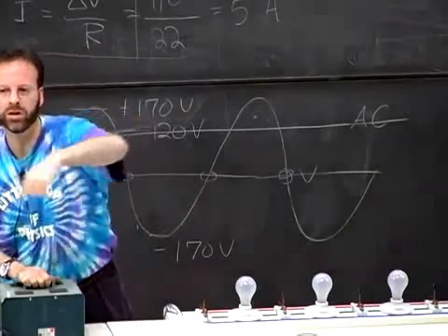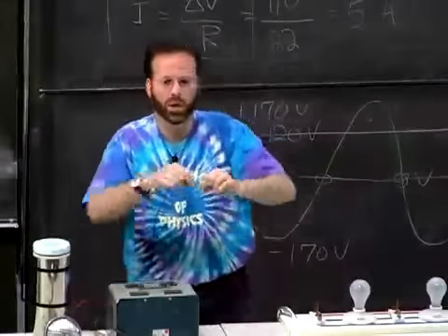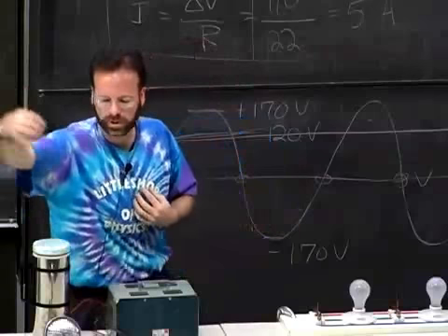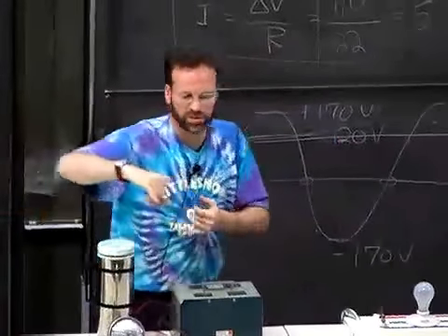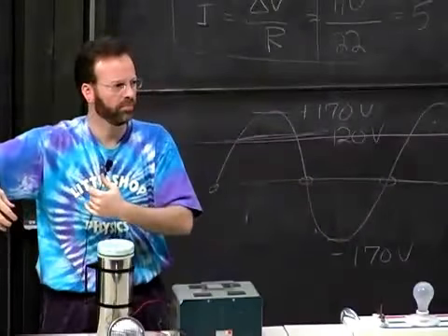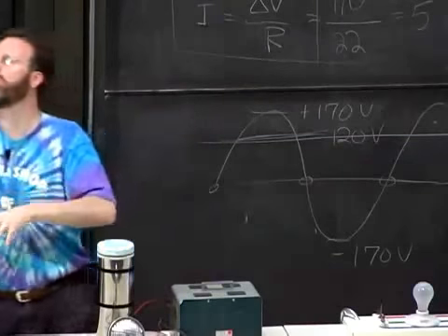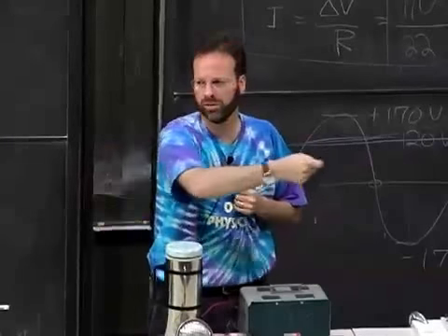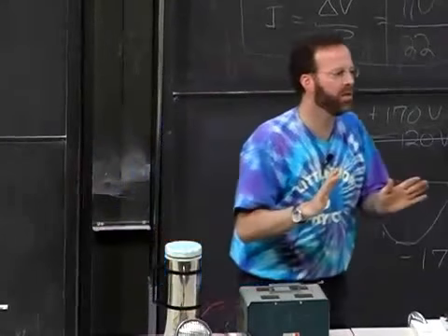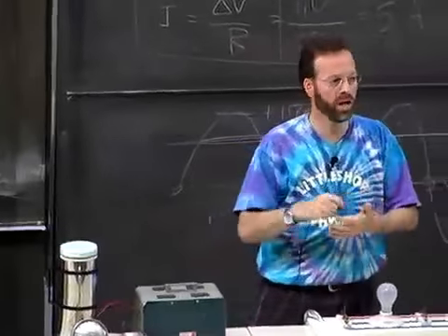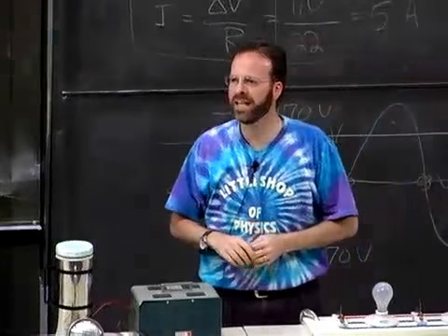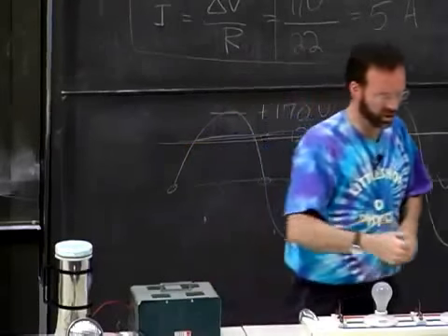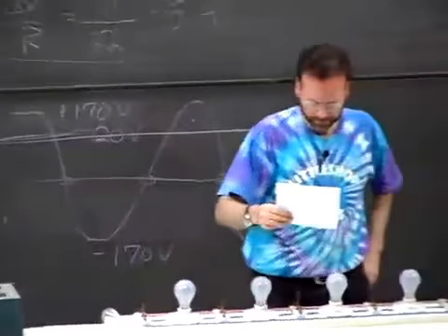And in a series circuit, that was series, where there's one path. In order to get through from me to the next person to the next person to the next, you have to get through them. That's why if there was a break, it would stop. There was no branching off. Oh, some current could go over here and some current could go over here. We had the same current going through each of us. The current is the same in a series circuit. You should note that. The current is always the same everywhere in a series circuit. I'll revisit it, but that's an important point.